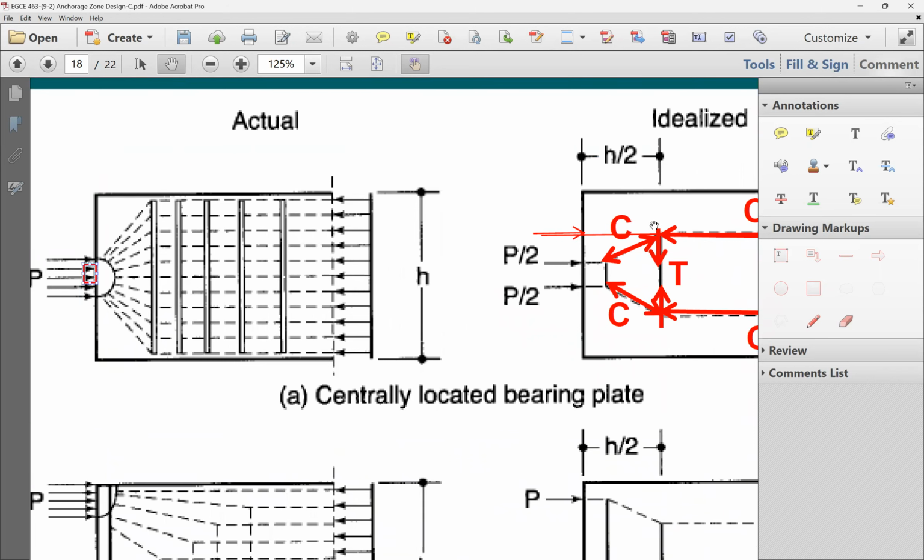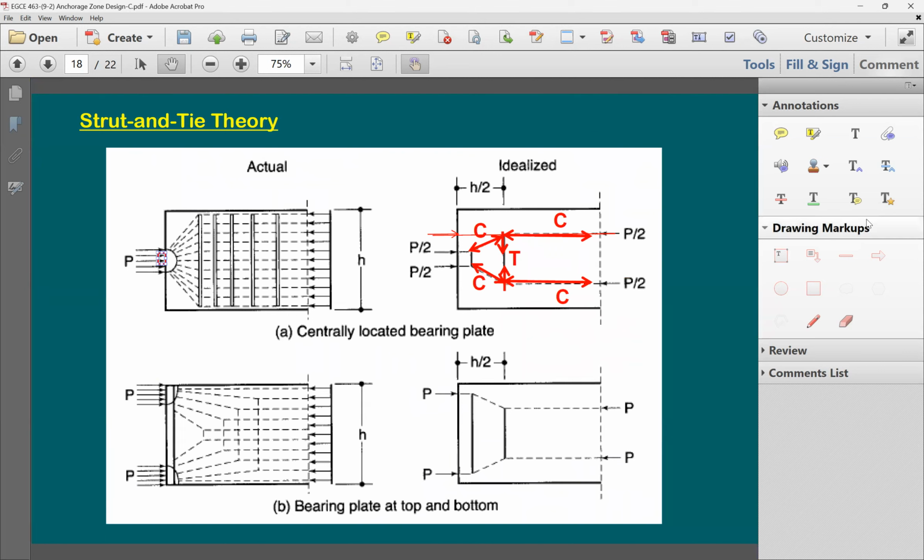So again, the location of this force here is going to be controlled by taking 1/2 of the force, which means 1/2 of the height. And again here, 1/2 of the height of the beam, of course, the beam total depth, and put a point load right in the middle in both of these two cases and come up with this location here. So the location in a beam like this is going to be controlled by simple analysis. Unless I have a different situation.